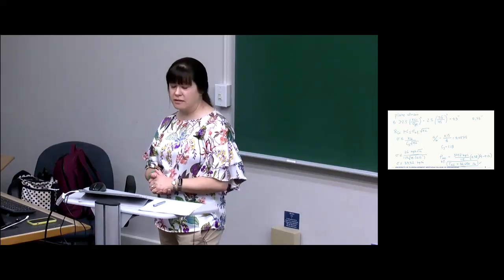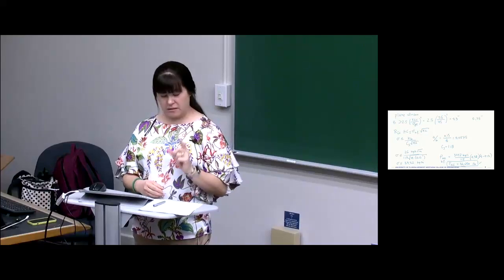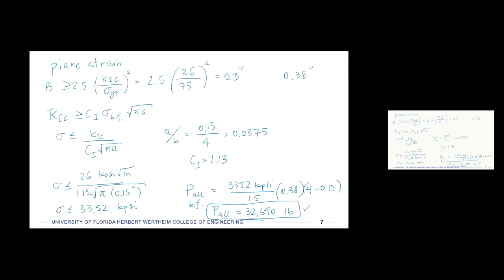If you do not subtract off the length of the crack, the 0.15, then you get a value of almost 34,000 pounds instead of 32,500 pounds. But in this case, I just wanted to be a little bit more conservative. Yep.